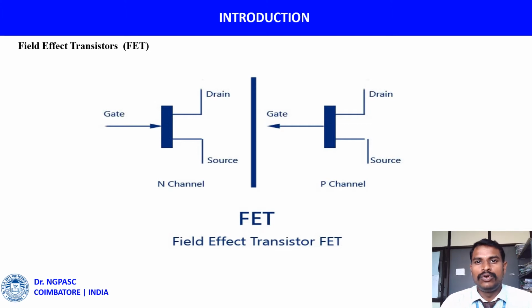Although the low input impedance problem may be improved by careful design and use of more than one transistor, yet it is difficult to achieve input impedance of more than a few megaohms. The field effect transistor has, by virtue of its construction and biasing, a large input impedance which may be more than 100 megaohms. The FET is generally much less noisy than the ordinary bipolar transistor.